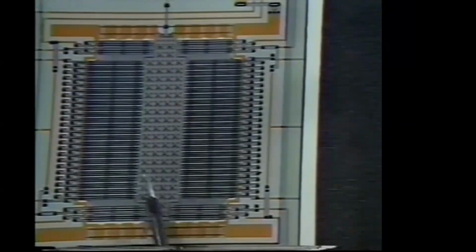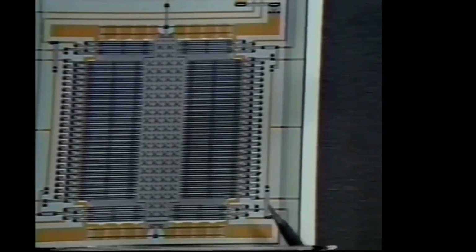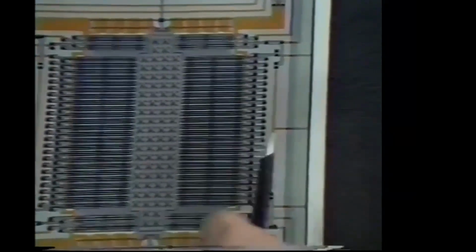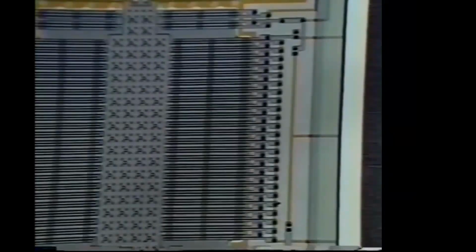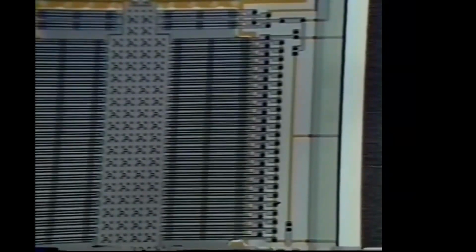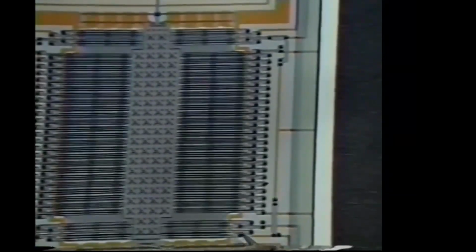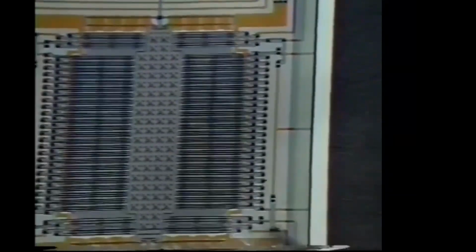Here you see a wider proof mass. This is a folded suspension which automatically stress relieves the polysilicon. And in some cases, we actually use the polysilicon as crossovers of some of the signals. That, and the fact that the sensor was placed in the center of the die, were some of the improvements. But in a force rebalanced architecture, you don't need all of the fingers to sense and all of the fingers to force. At 5G full scale, we separated force and sense, again allowing a reduction in the noise and improvement of the overall system performance.